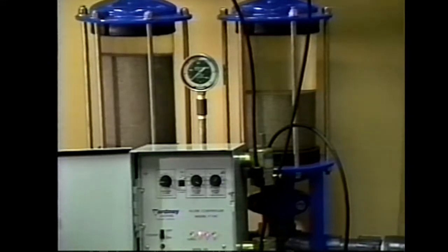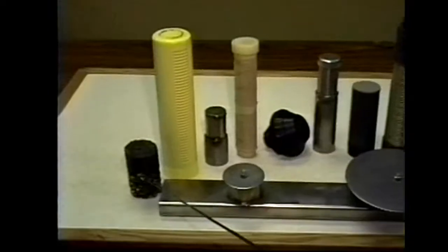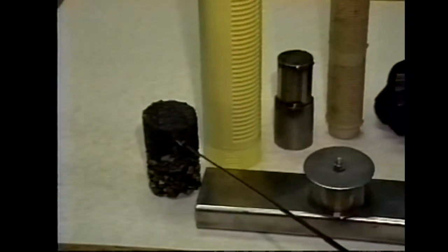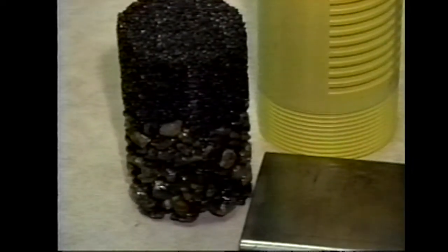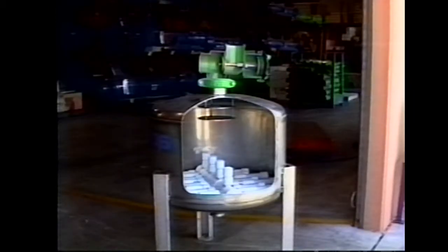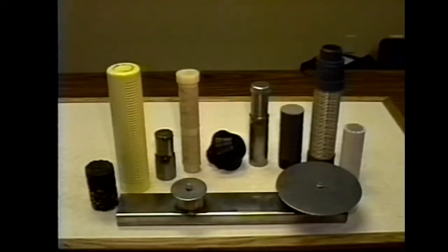Not all underdrain designs provide for such uniform uplifting of the media bed, as seen here. A mineral aggregate mix is sometimes bonded together with epoxy and cast directly into the bottom of the tanks as an underdrain. This design has the lowest pressure loss and most uniform dispersion of water, but it requires excellent maintenance and backflush adjustment. Some lateral or slotted underdrains are very reliable and also have large open areas. However, there are major differences between various designs and their effectiveness.